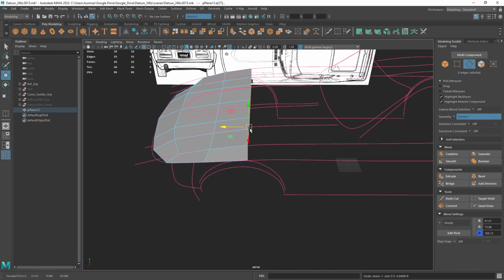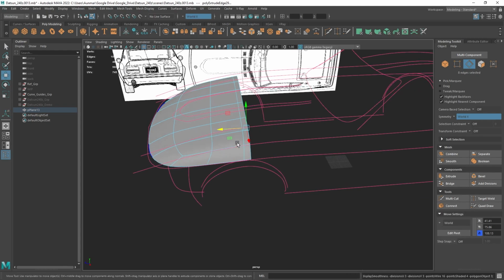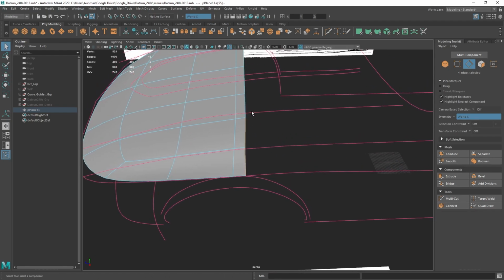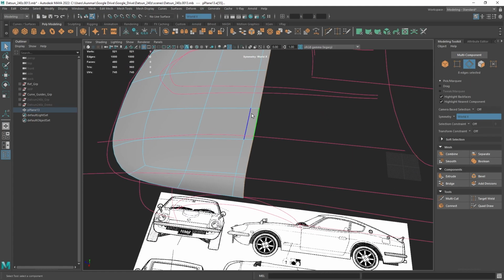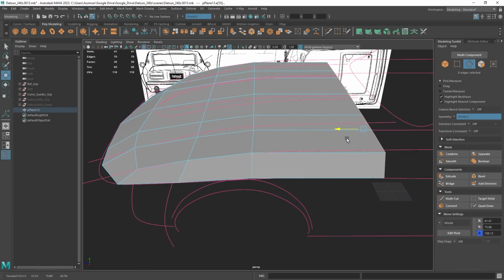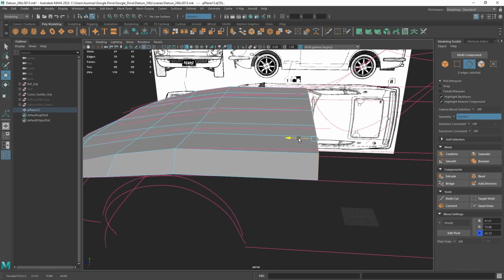And if it does that, no worries, just hit Control E to extrude, and then you can just simply move it. Grab that edge. Now I did use smooth preview, so I can kind of easily separate that with 3. So you can use 1 and 3, okay? And 3 is smooth preview, and 1 is normal mode. And there we go. We can just kind of move that and select those edges, all right?